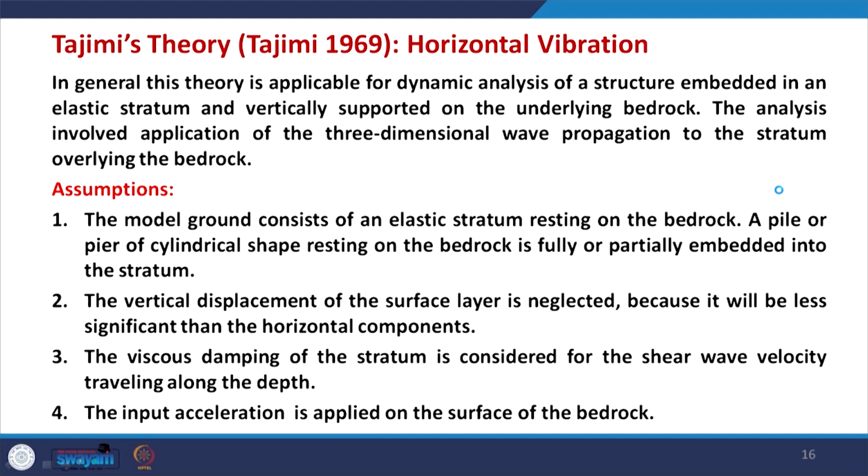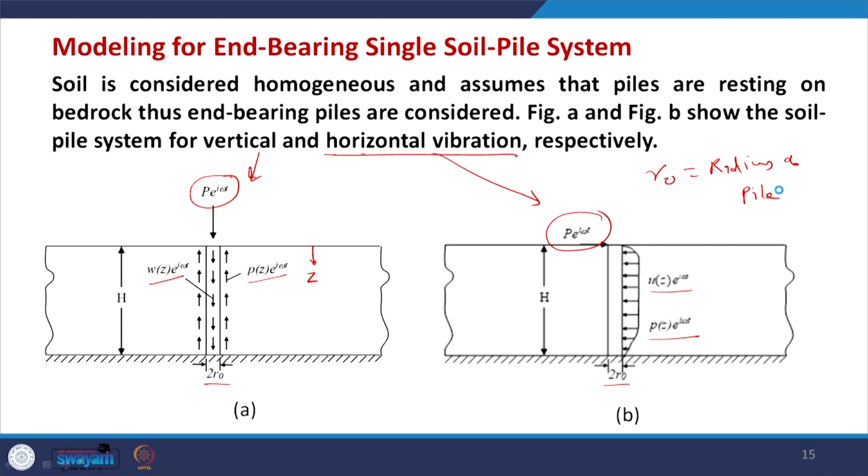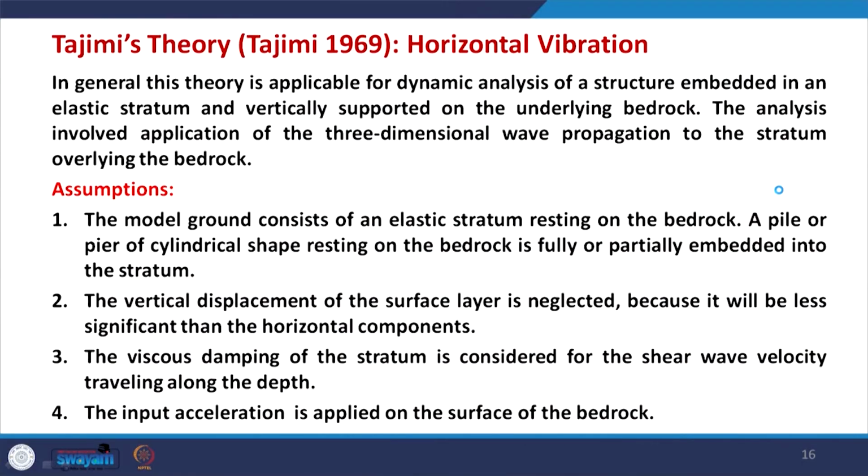What are the assumptions? The model ground consists of an elastic stratum resting on the bedrock, and it is assumed that the property is elastic. A pile or pier of cylindrical shape resting on the bedrock is fully or partially embedded into the stratum.